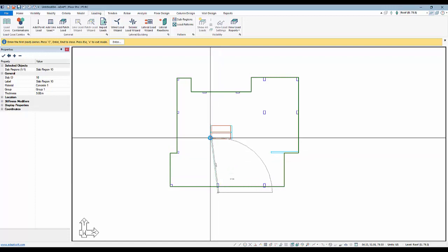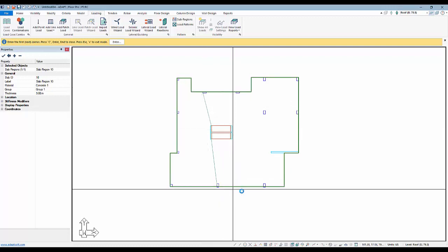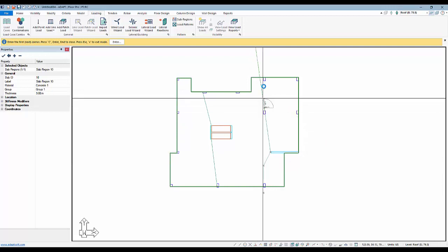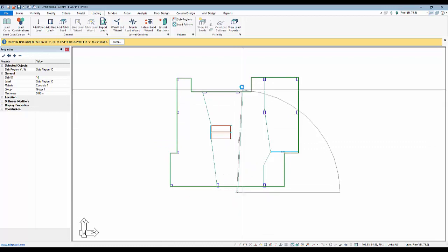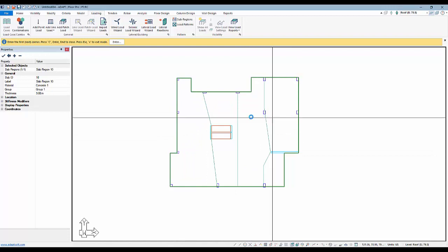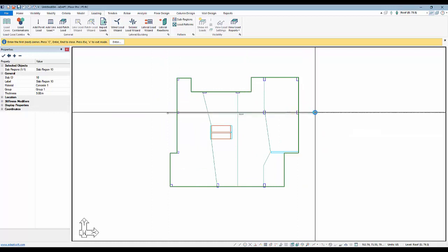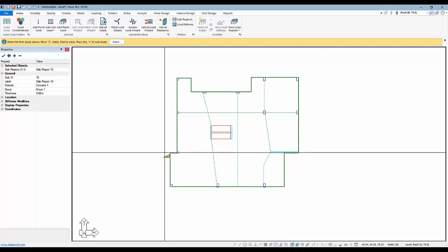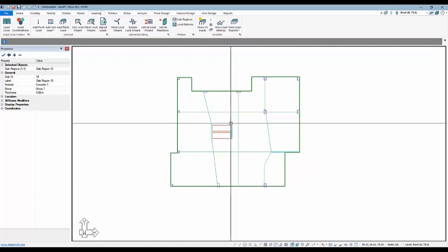So I'll select, for example, something like this. You could put these in orthogonally also. There's no requirement to do what I'm doing here. So we'll just have 4 regions here, 4 strips rather. And then in the other direction, I'm going to add these lines. If we want these orthogonal, we can actually use the snap orthogonal mode, like so. And so we have our subregions.